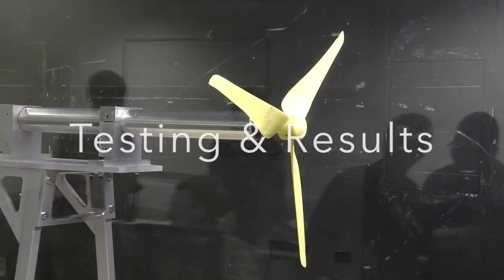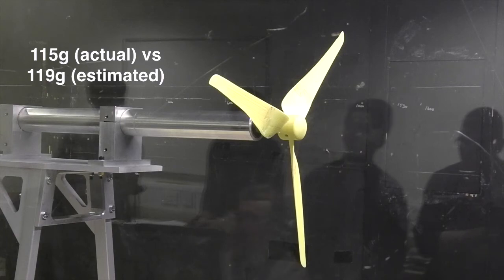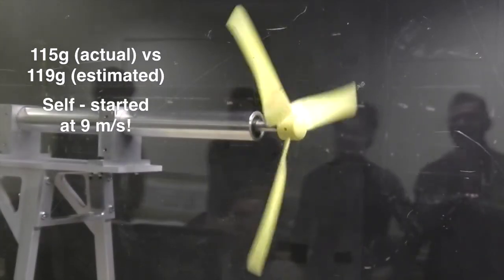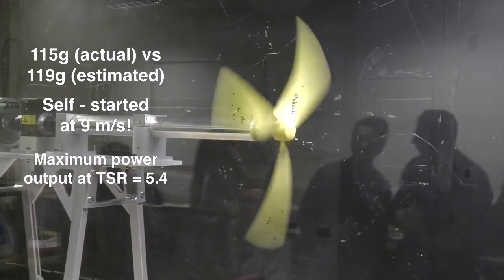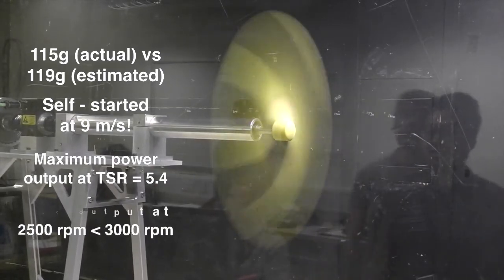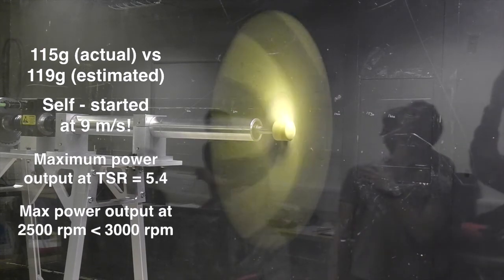Our manufactured wind turbine had a mass of 115 grams, slightly lower than our design mass of 119 grams. After a tense few minutes, the wind turbine successfully self-started at a wind speed of about 9 meters per second. Unfortunately, the maximum power output occurred at a TSR of 5.4, which was higher than our design TSR of 4. However, the RPM at this maximum power was around 2,500, well below design specifications.